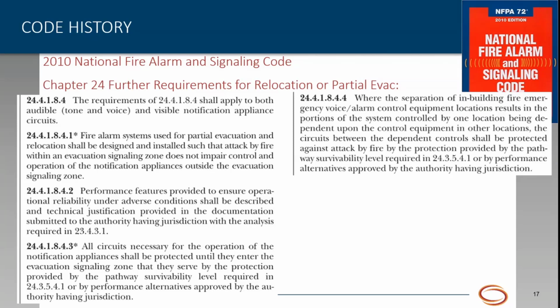Second, we see a requirement where there's a separation of control equipment, again, like a network or a fire alarm control unit to a transponder or some other subordinate panel. If you're using distributed amplifiers, distributed NAC panels or power supplies, any of those kinds of things, where you have a separation of control equipment where one unit is dependent on another for action, it requires the interconnection circuits to be survivable. So those may be SLC circuits, they may be network circuits, they could even be NAC trigger circuits. All of those would fall into that requiring survivability.